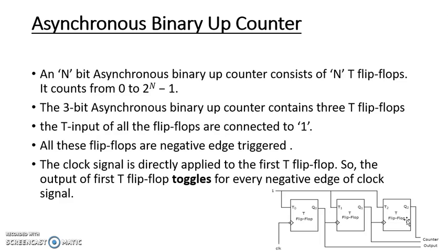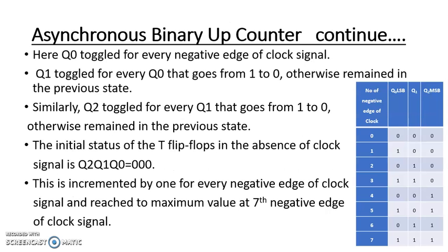Now we'll see the counting operation, how it operates. If you observe the truth table of the counter, in the initial condition, the outputs of all the flip-flops are 0 0 0, which is the reset condition.